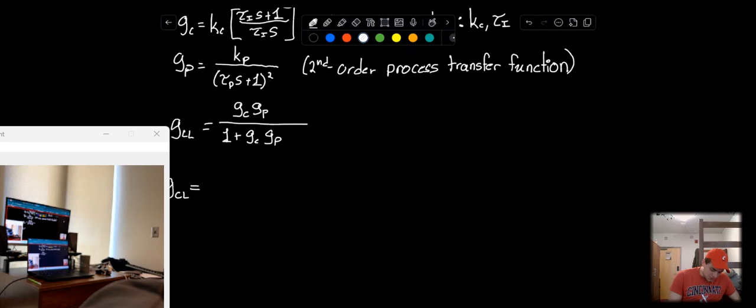It's going to be equal to Kc times tau I s plus 1 over tau I s, times Kp times 1 over tau p s plus 1 squared,